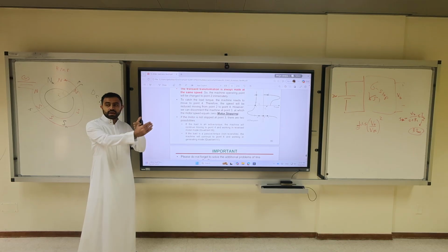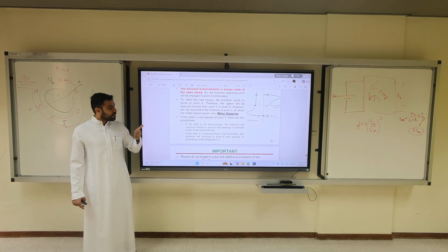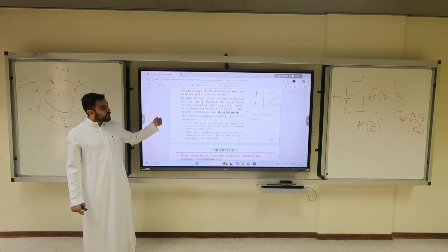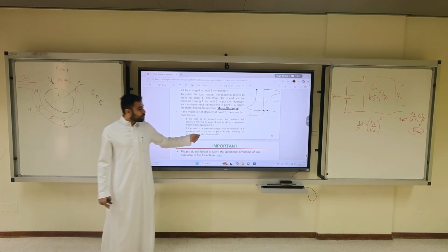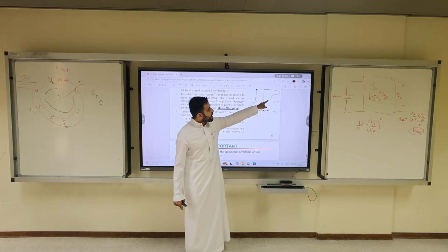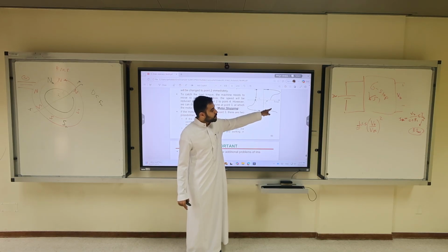Basically, we exceed the supply speed. For non-active load, we have to use counter current and go to quadrant 4 into the generating mode. So if you have an active load, you just go here to generate.